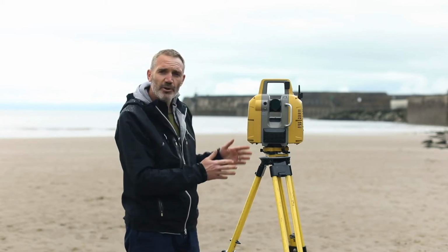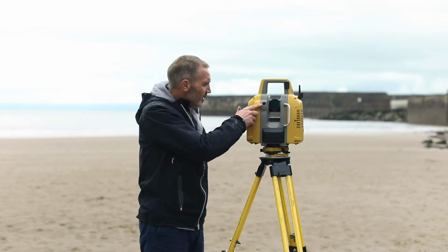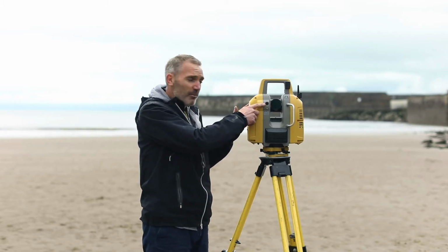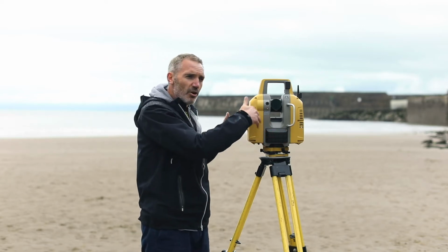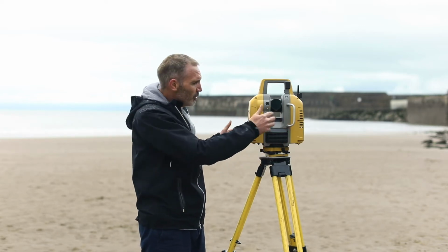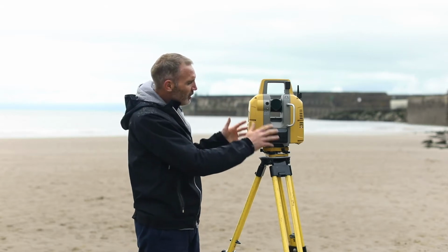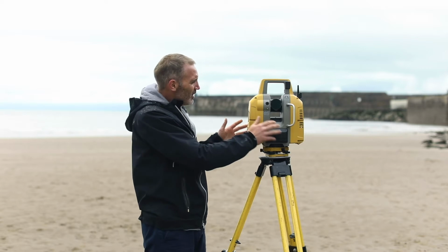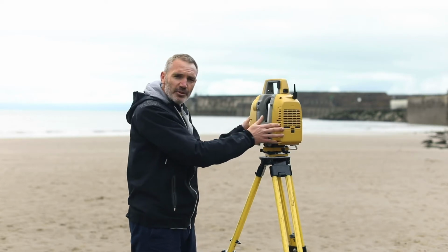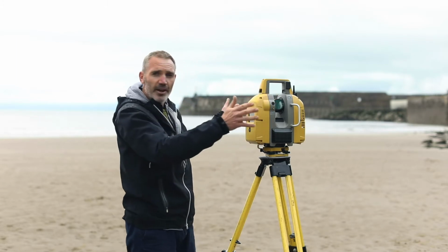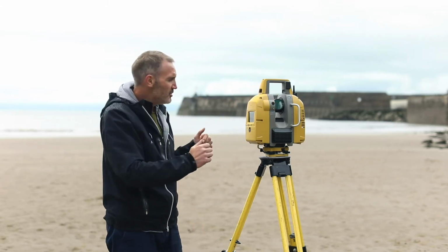But there's one other component of these laser scanners, and that's this other little lens here. And this is an actual wide-angle camera. And it's possible to acquire not just 3D data points, but also 360-degree photography. So if we choose that option to take the photographs, the first thing the instrument does is just move around in about 8 positions and take a wide-angle photograph to give us a 360-degree mosaic of imagery.